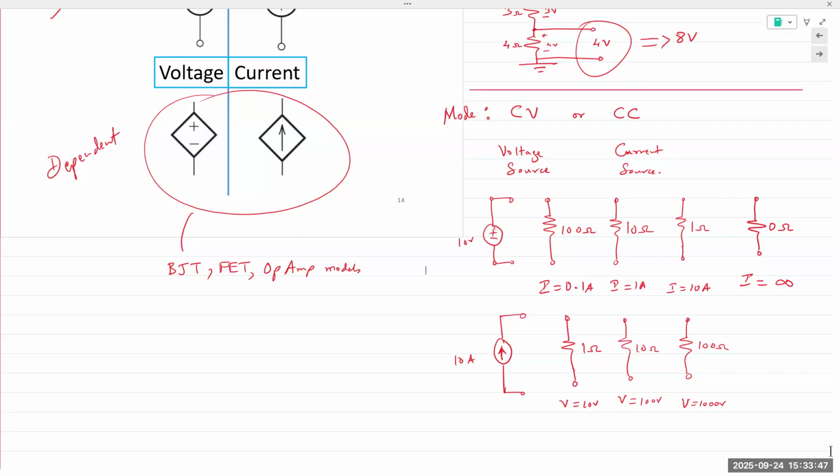There's a short circuit, and the resistance is 0. It doesn't matter how small the battery is, current is infinite. What happens when there's a closed loop? Electrical energy is supplied. If it's a very small battery and you have a short circuit, it's going to supply the energy until it's exhausted. Even a small battery still has tons of capacity. So if you take a small coin cell and you go on the beach, don't do it, but I'm just saying, if you want to do it, go on a beach surrounded by sand with a small, old coin cell, and you short the terminals. If there's some capacity left, it's going to expend that energy. That energy is dissipated as heat, so it gets hot.